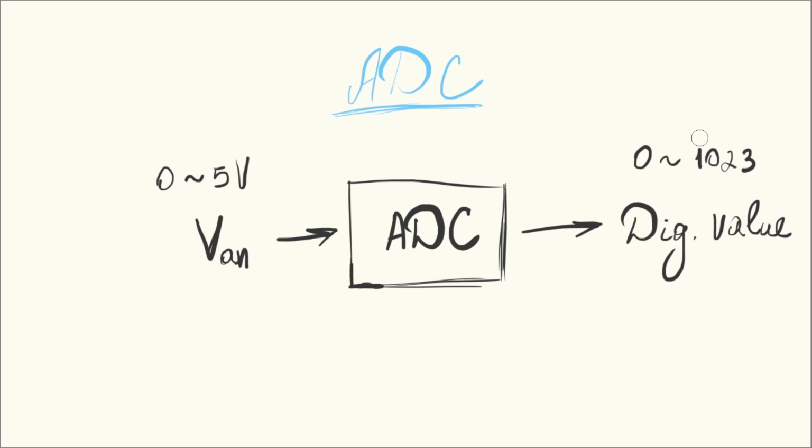I think AVR judged 8 bits would be too small, giving imperfect readings, but 10 bits would be okay. You don't need to actually care about this because AVR already did it for us, and it will be stored. We will access it using only one variable. This variable, I should say macro, not variable, will be called ADC.